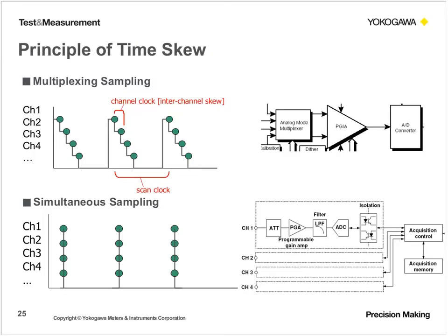With these types of data acquisition systems, you definitely have a lower cost per channel, but at the same time, you're not simultaneously sampling each channel. So if you aggregate the delay across each channel, that delay can really add up, and it can really have an impact on the measurement error that you're dealing with.